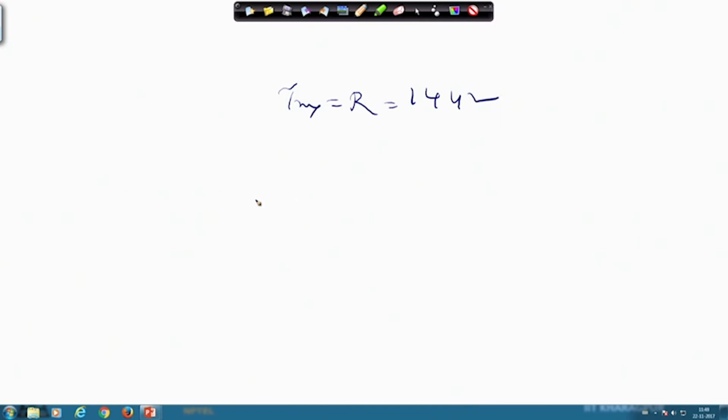Already the plane was at 16.85 degrees. If I draw horizontal, the normal was at 16.85 degrees, that means the plane of maximum shear stress is 45 degrees with this. So, I can go further to make 45, that is 28.15, from here to here I can go 28.15 and draw a line. So, this is the direction.